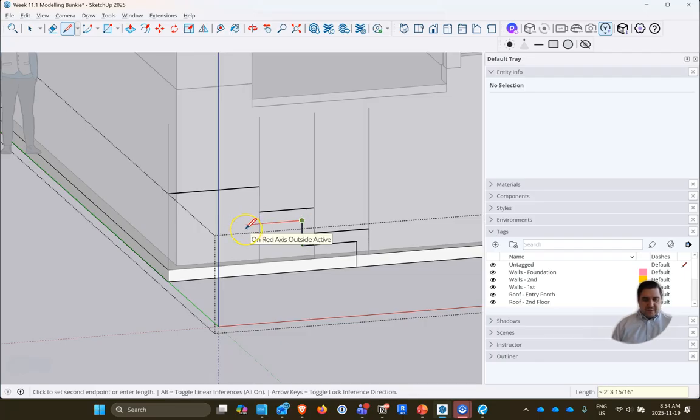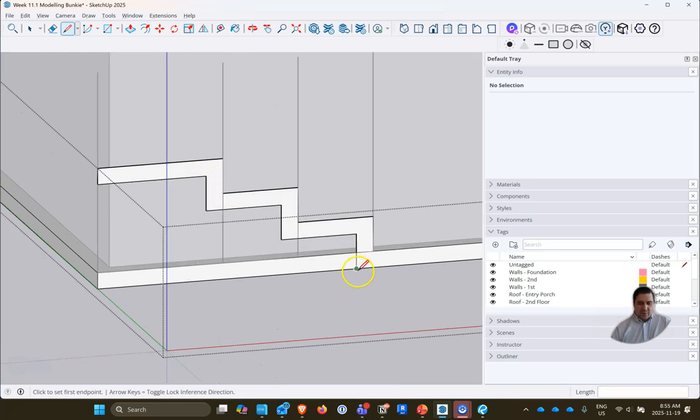And the reason why I'm doing this first, 2 foot 3 there, is now that we have these lines, it's easier to create a slope. So it's easier to create that sloped area that you would see in our footings. And we're just tracing the bottom of our footing part. And so with this, we can grab this bottom line now, and we can come up on a 45-degree angle.